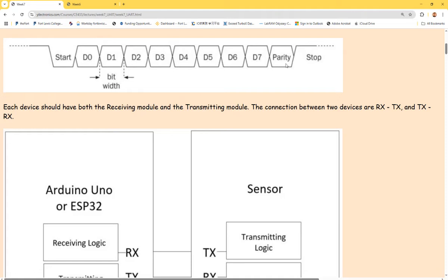Remember how we generate the parity bit for the sender? Yeah, XOR, right? So you can have a parity generator in your transmitter module and just put it into a concatenation, the curly bracket. You can directly force it to be the parity bit. We'll see the code in a bit, okay? So you are able to do that easily. So put that parity bit with your data byte as a package, and eventually send everything out